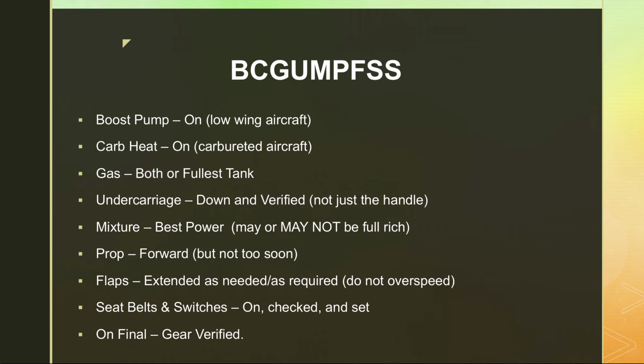But you do want your flaps down as needed or as required. Okay, heavy crosswind, maybe you don't want full flaps. Short runway, you do want full flaps. Seatbelts and switches. So that's my S and my S.